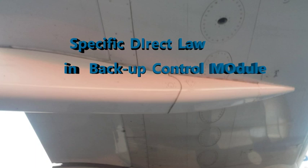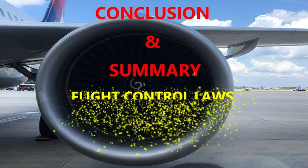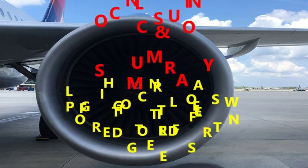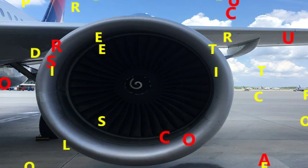Okay, they're programs. So that gives you an idea, and the whole idea here is just different levels of protection for the aircraft in different phases of flight. And just keep in mind that it's a degradation. What I just said, in the order that I presented them: normal law, alternate law, direct law, and abnormal law, is the order from the highest level of protection to the lowest, or pretty much the lowest, where there's no protection.